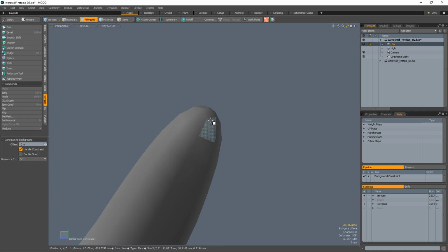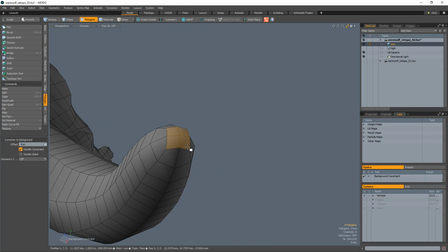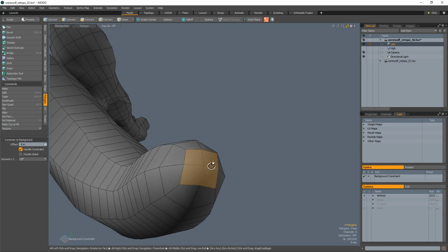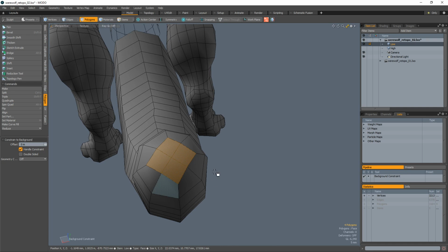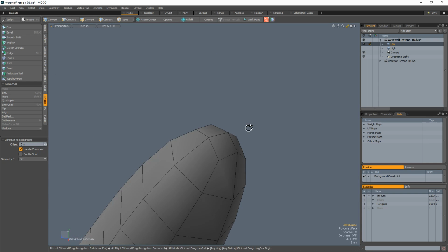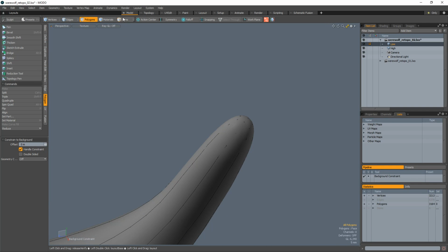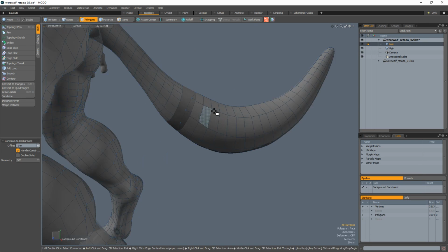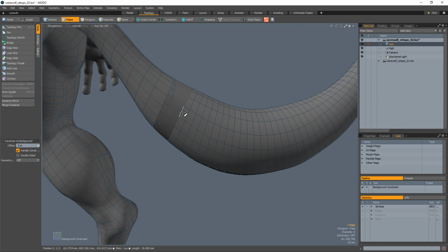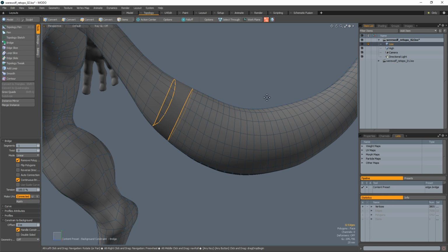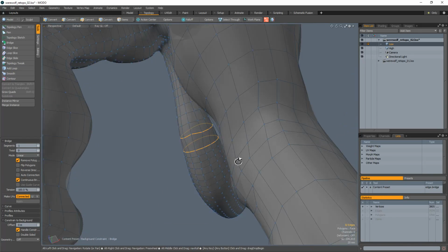And finally, there are some fun things that you can do with 8-sided polygons and such in here to cap things off. You know, I could rotate the center lines along here so that things connect a little better. There's really a lot that I can do just in here with some simple quads. So let's do one more subdivision. Because this has 8 sides, if I subdivide it one more time, I can then bridge this gap. And it's already pretty even.